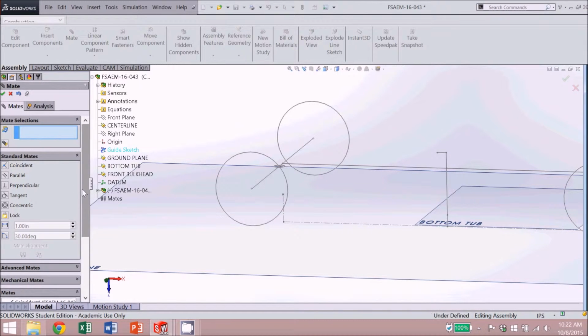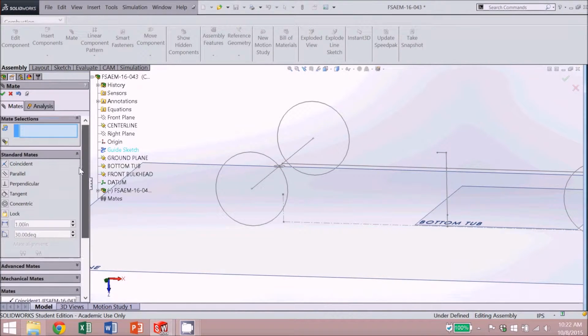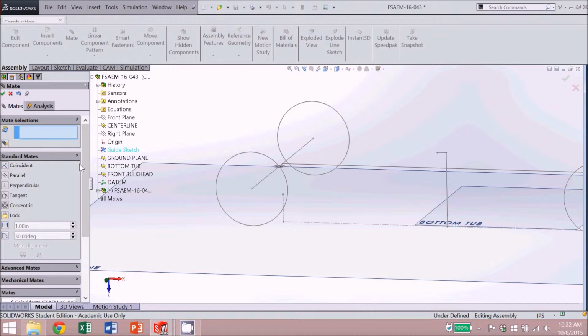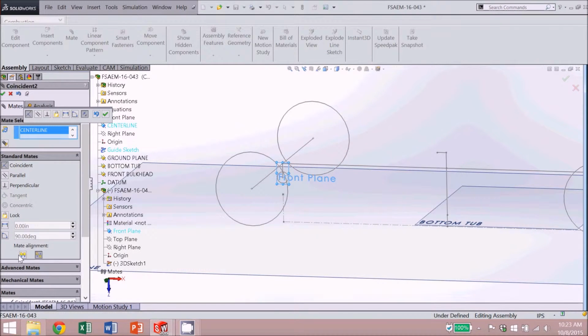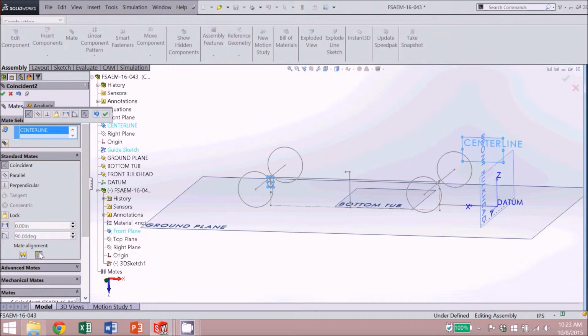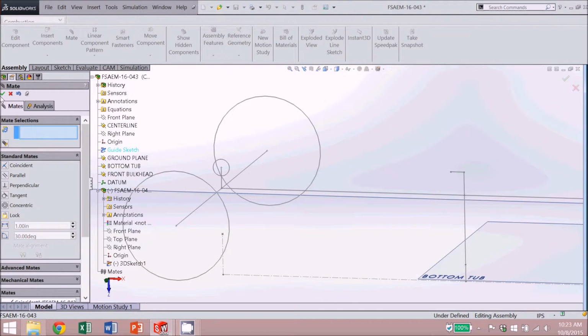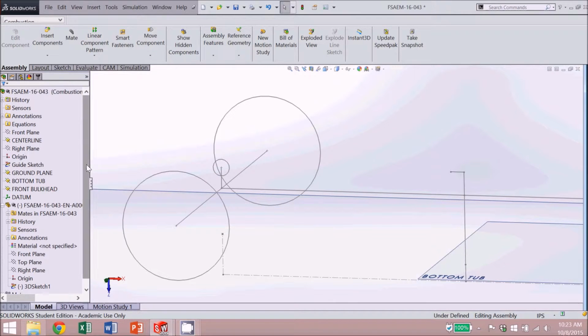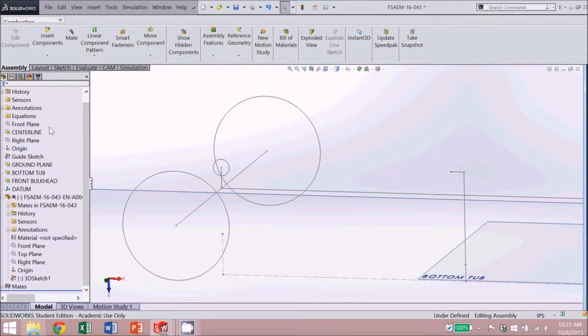And hopefully you can start seeing how laying these lines out allows you to change certain features on the fly when you need to. And I just dimensioned it to these three planes over here, which are our datums on the car this year. So now that we completed inserting it, let's start editing the guide sketch so that it's useful for us.